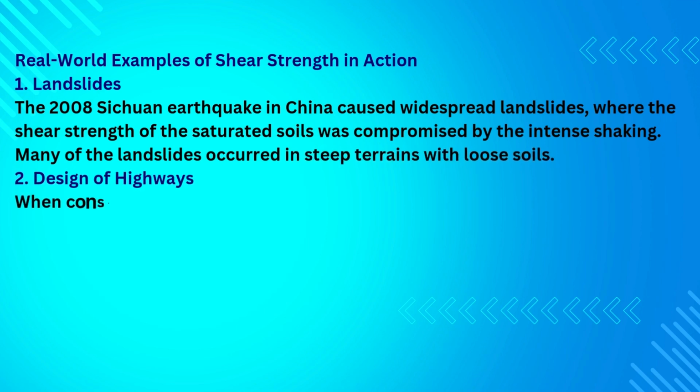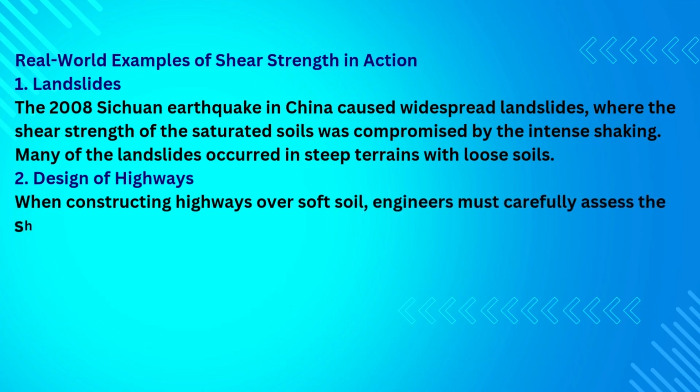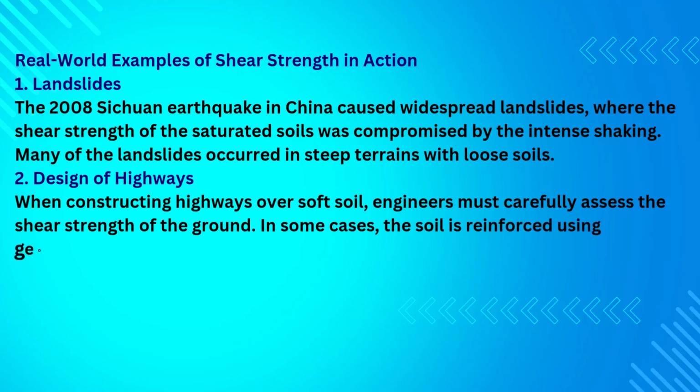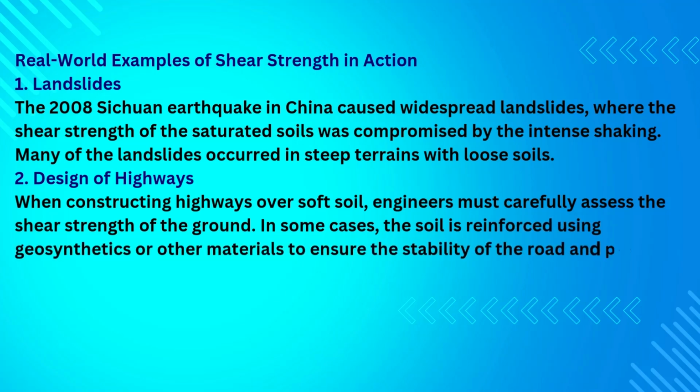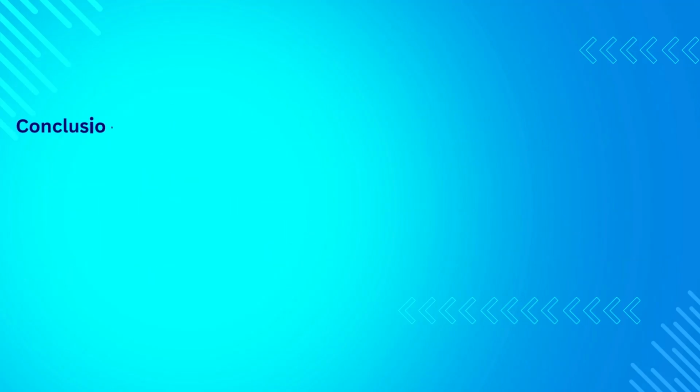2. Design of highways. When constructing highways over soft soil, engineers must carefully assess the shear strength of the ground. In some cases, the soil is reinforced using geosynthetics or other materials to ensure the stability of the road and prevent shifting or sinking. Conclusion.